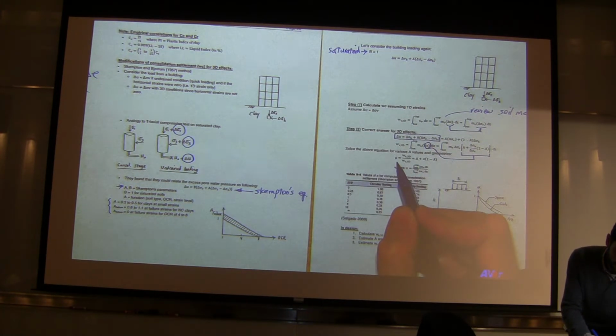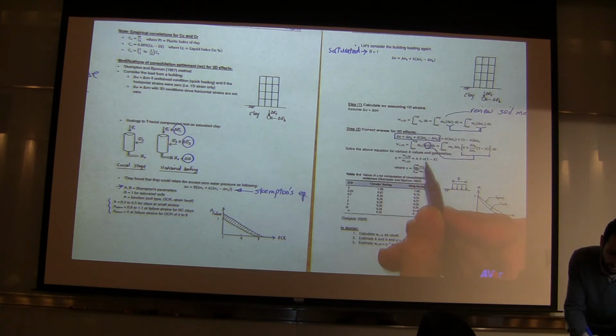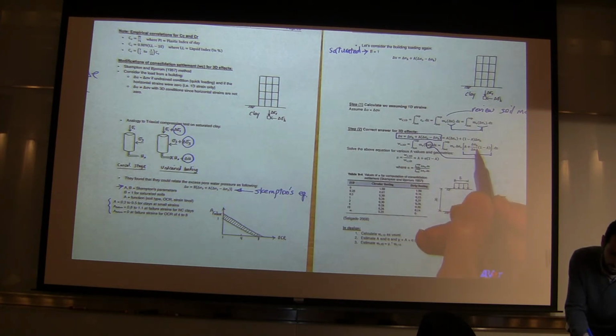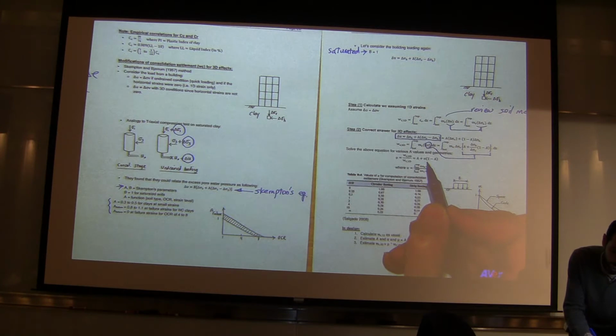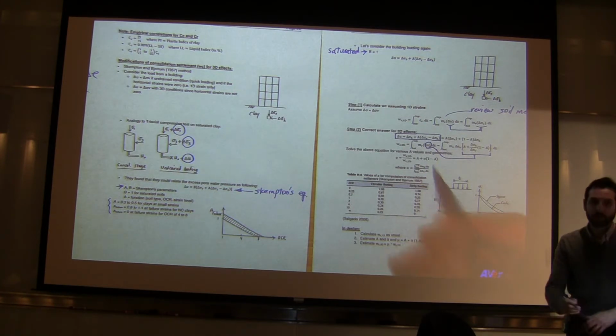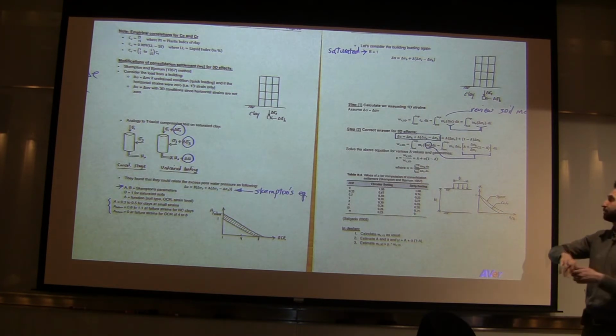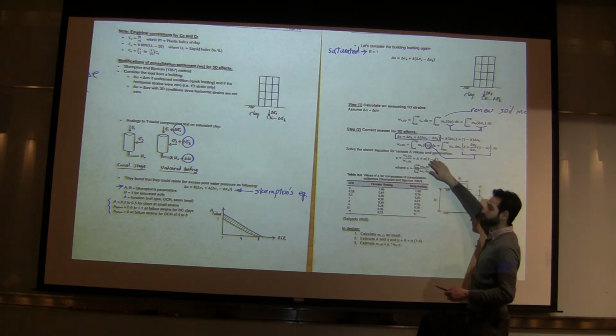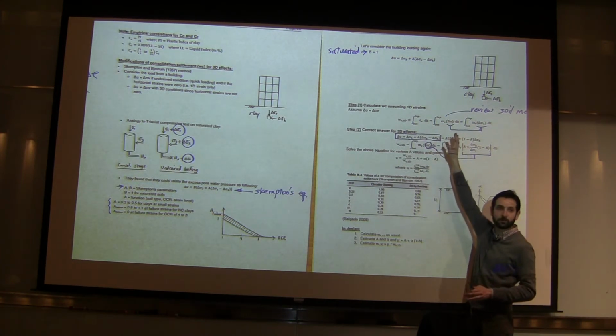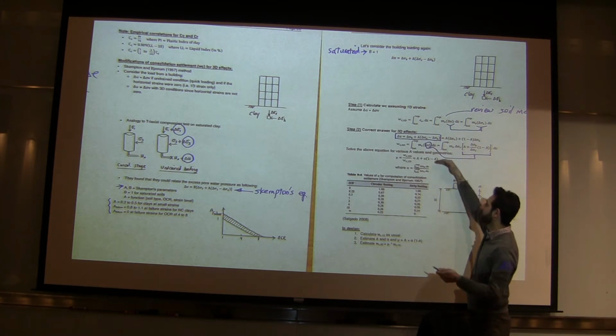What this tells you is that you can calculate something called mu, which is the ratio of consolidation in 3D versus the consolidation in 1D. And that's A plus alpha. Alpha is this delta sigma H over delta sigma V times 1 minus A. So without getting lost with how I got to this point, let's just start from here.